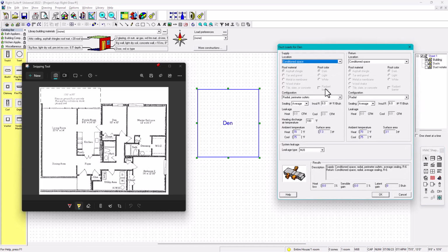Now, in this case, where is my supply duct located? In my case, because it's a condominium, and this condo unit is in the middle, on the second floor, with the first floor at the bottom and the third floor above condo number 2, it's in the middle. It's like a sandwich, right? So my ducts are completely in a conditioned space. Return in a conditioned space. That saves a lot of energy, honestly.